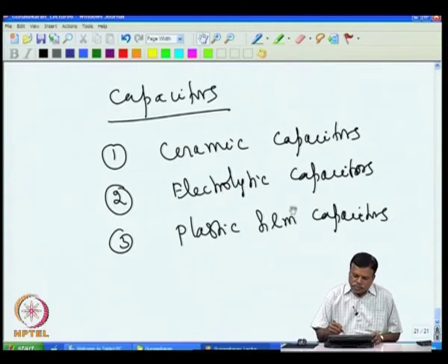There are also various other properties which we will see in the next class, but we have to worry about these properties and select capacitors correctly for proper use. In this class, we showed the errors in the temperature indicator circuit: drift due to the Zener, offset voltage drift error, and resistance drift error.